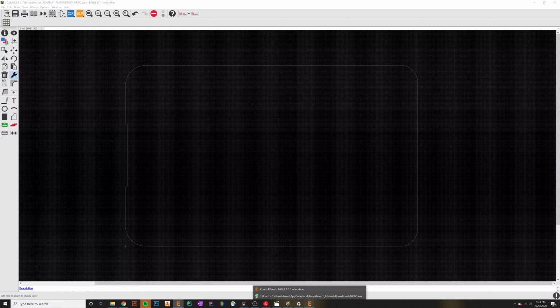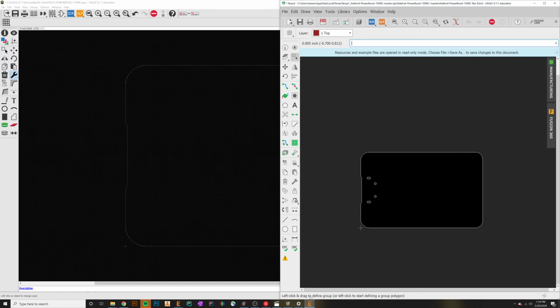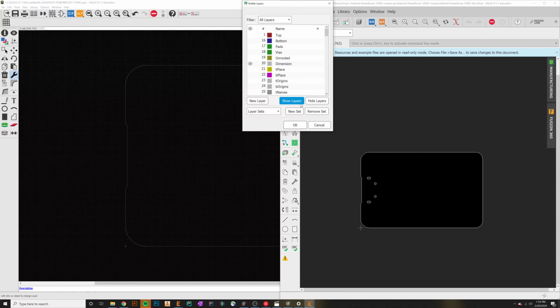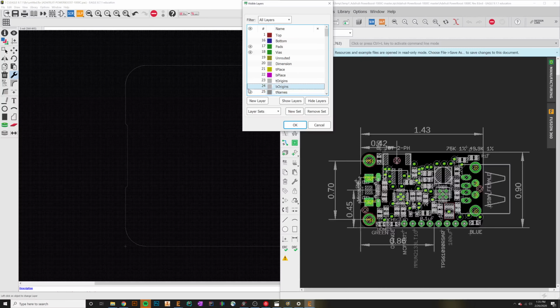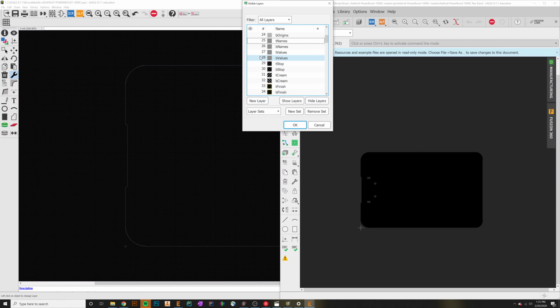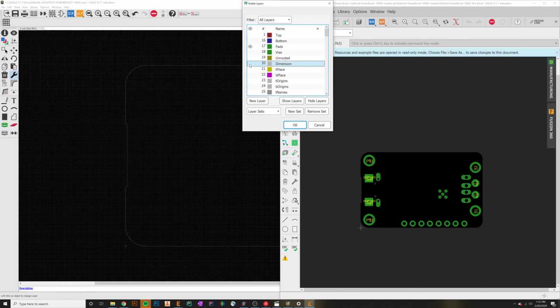The next step is to figure out what the distance of that center point is from the rest of our design. So to do that, I'm going to go back to our layer settings in the previous board, and show all of the layers again. Actually, it's kind of difficult to see things in this view, so I'm going to start to get rid of some of these. I want to keep the pad because that is the actual circle. I'm just going to hide all the layers and only show the pads. I'm happy with that, and then I'm going to hit OK.